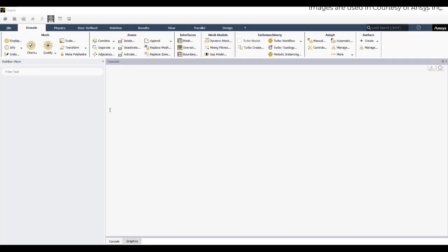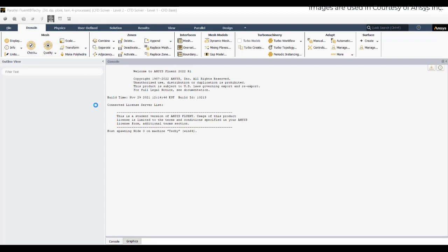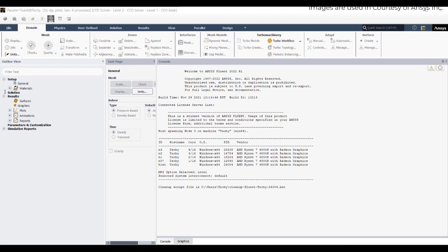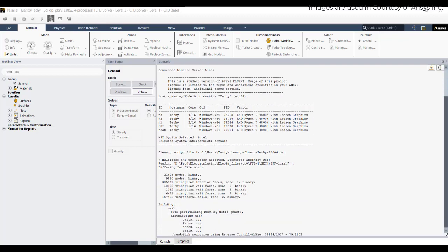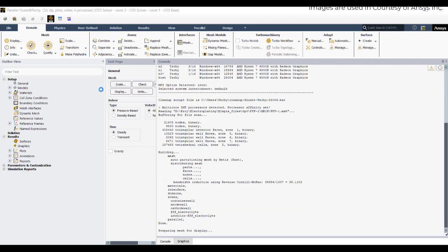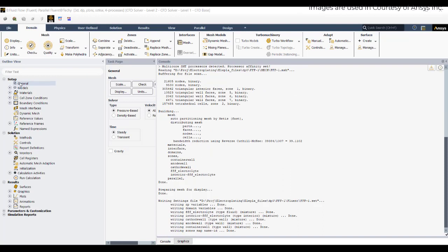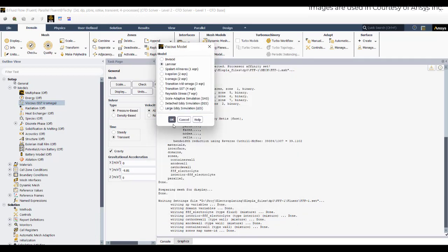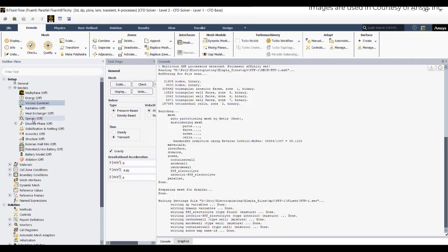I've switched on the fluid. Here we will do a transient simulation because the deposition varies with respect to time. Go to general, click on transient. Here we don't bother about the energy properties because we are taking a constant temperature. I just change it to laminar. It doesn't matter because we are not really bothered about the flow here.